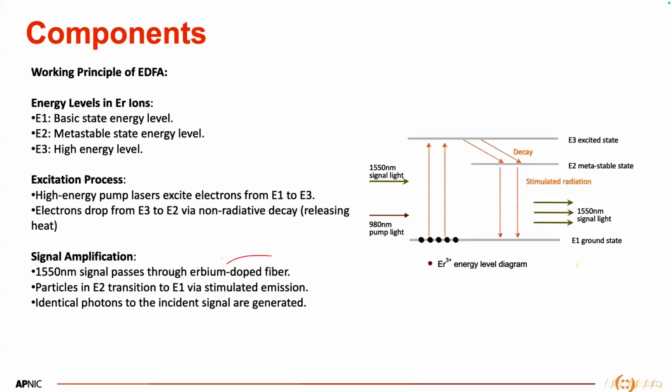When the light comes into an amplifier, we use a laser pump to pump lasers, and three states are there: the basic state, the metastable state, and the high energy state.